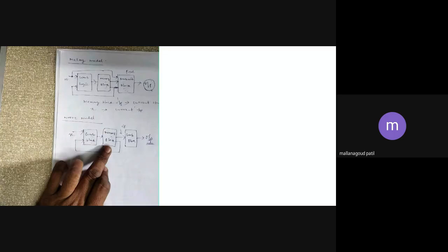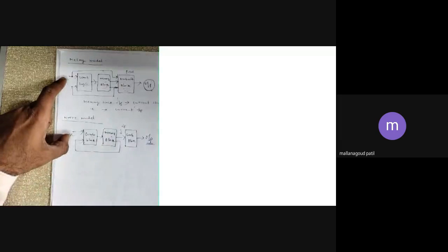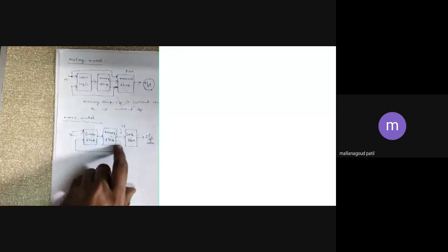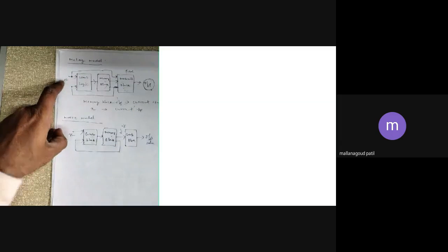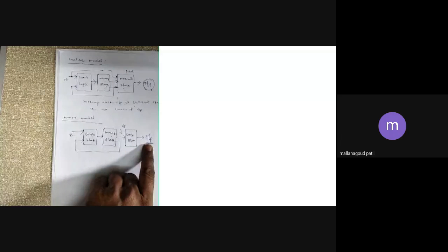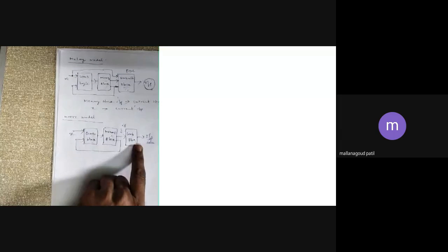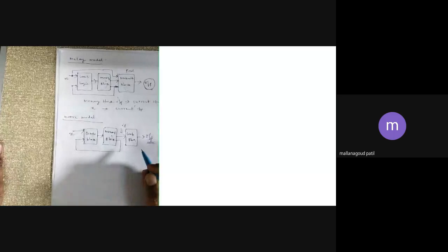the output of the Moore machine only depends on its current state and not on the current input. Here the current state is memory, but the current input is X. The output for the Moore model is not dependent on X. And the number of states here will be more. With an example, you will come to know that the Moore machine's number of states will always be more than the Mealy model. The output is placed on transition.